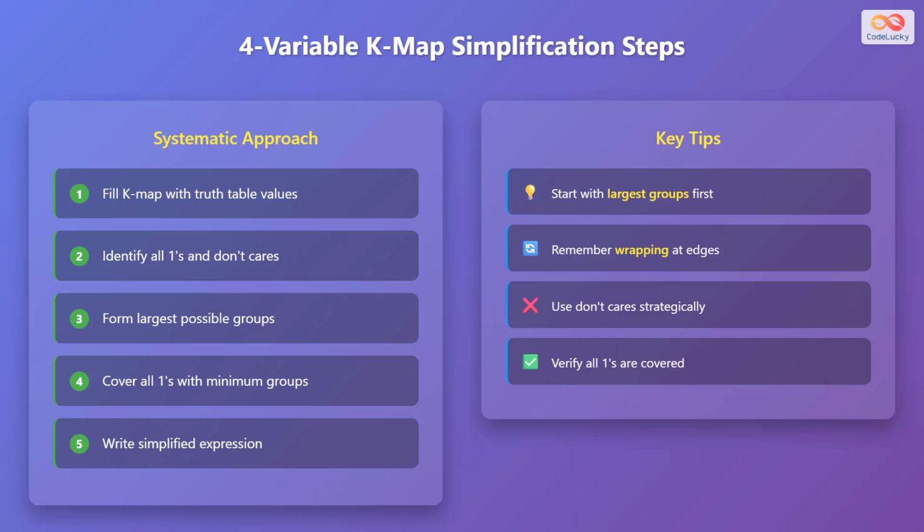Some key tips to remember are to start with the largest groups first. Remember wrapping at the edges. Use don't cares strategically and verify that all the ones are covered.